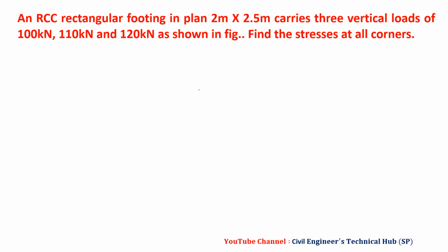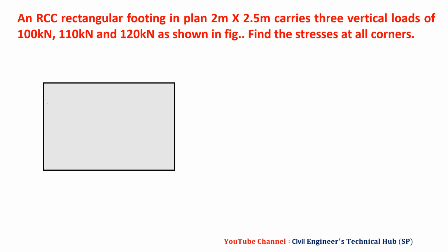Then we have an RCC rectangular footing in plan. So we have this value as 2 meters. This value we have 2.5 meters. And the first load we have given is 100 kilonewton, at 0.2 meter and 0.3 meter, that is from the x-x axis and from the y-y axis respectively.